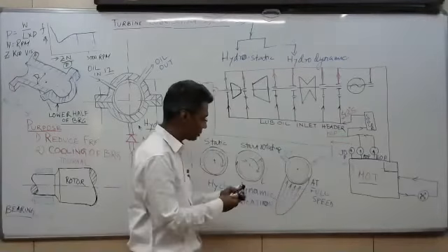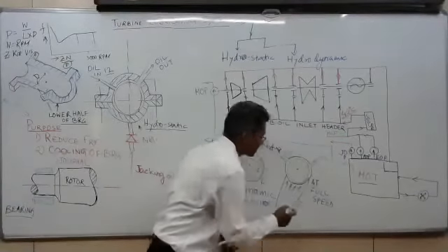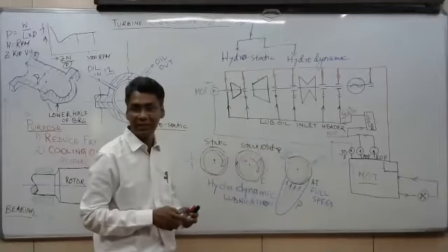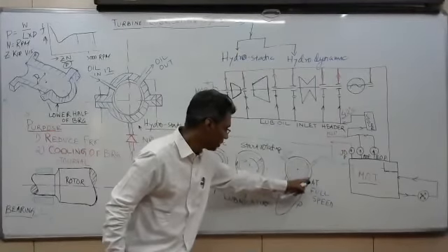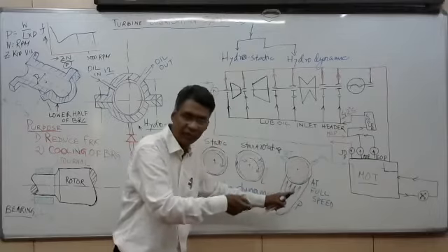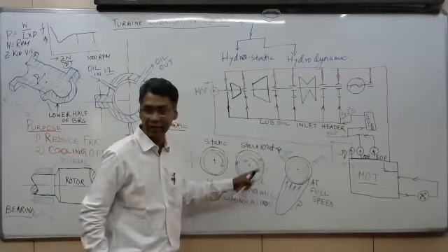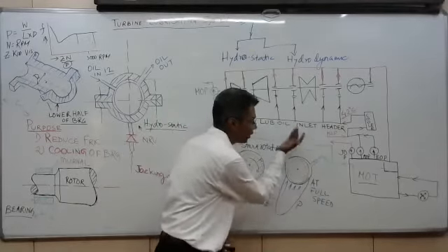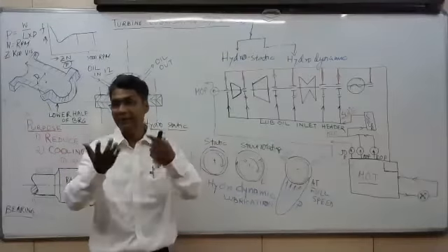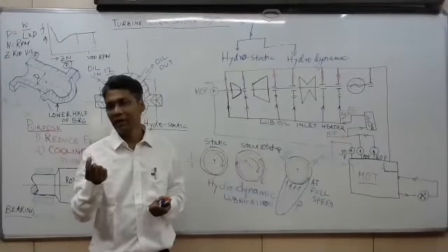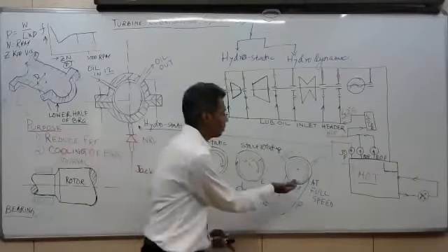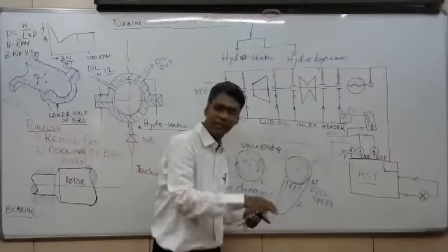That is the pressure distribution of oil. How the oil film pressure is developed over here. Initially, the pressure here is 0. As the thickness is getting reduced, the pressure is becoming higher. So that oil pressure is actually holding the complete load of the turbine, generator, or whatever. This very thin oil layer is holding the load.